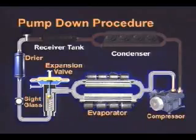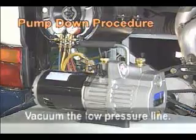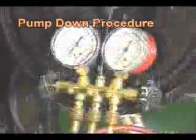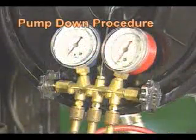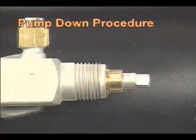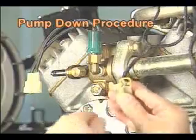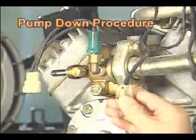Repair or replace the low pressure side's components. After the work, vacuum the low pressure line. Lastly, remove the manifold gauge and then open the receiver tank service valve and close the low-high pressure service valve and reconnect the low pressure switch.